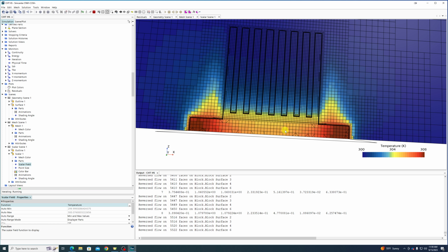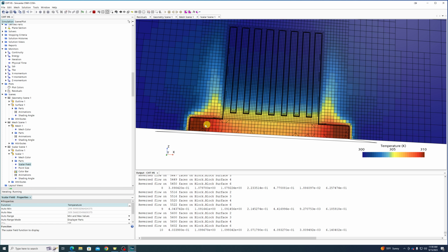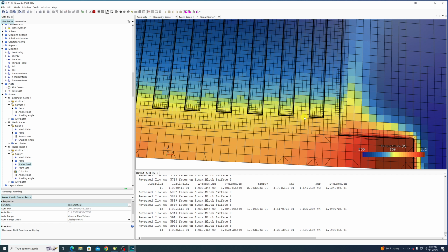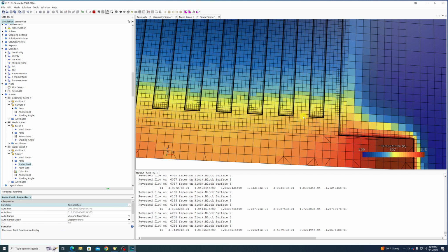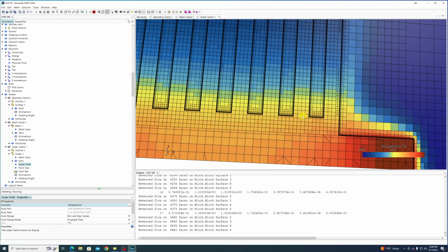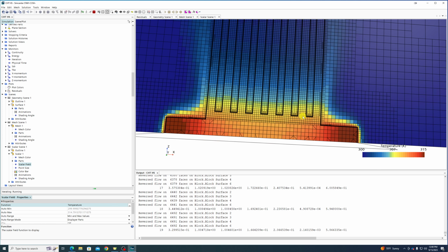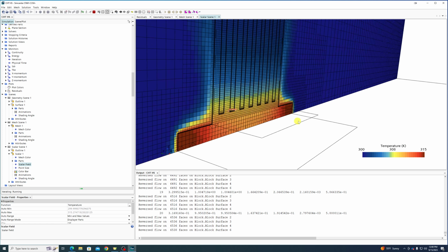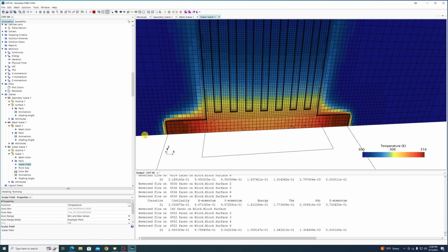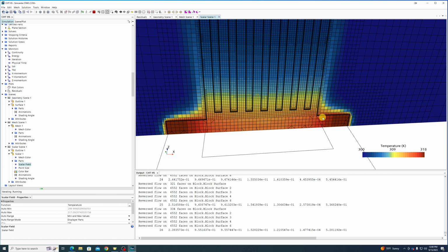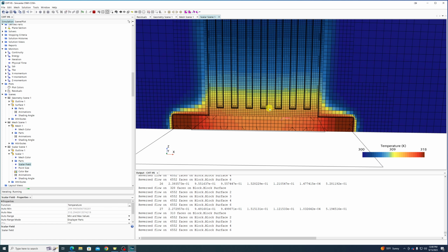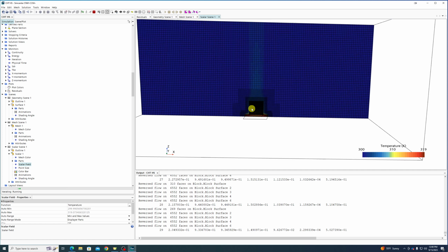Yeah, this is going to run a lot slower. But we're getting heat going from the first solid into the second solid. We can see it's working its way up these fins. Notice the edges of the chips are, according to this, the hottest. Realistically, the heat would probably be concentrated in the center of the chip, so you wouldn't get these hot spots as pronounced in the perimeter. But nonetheless.